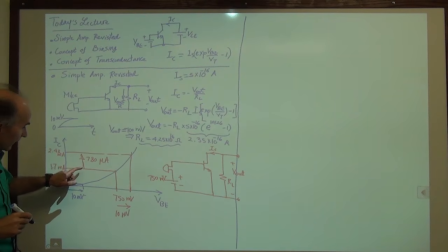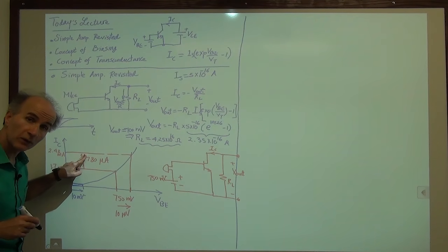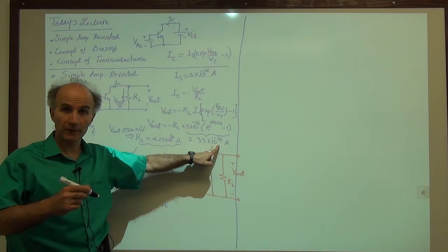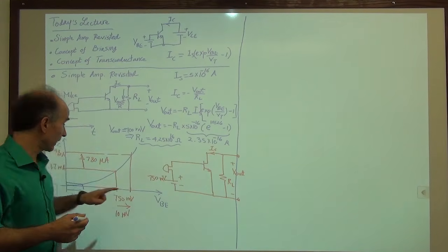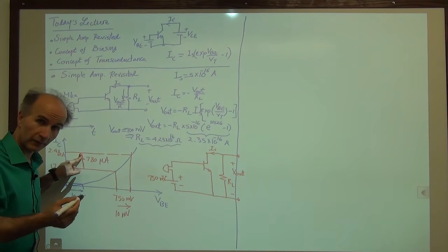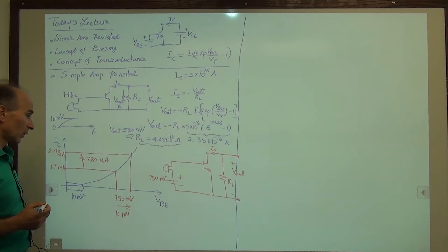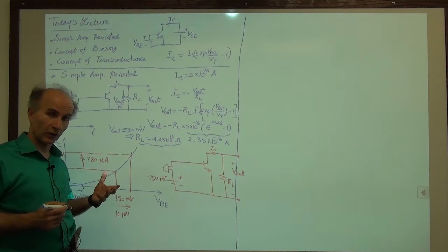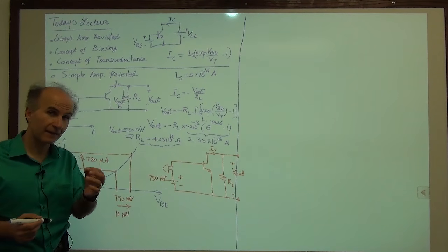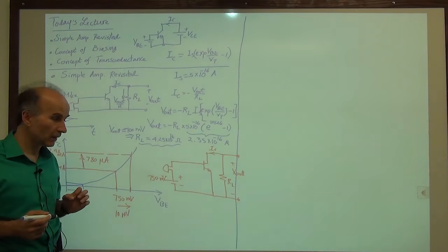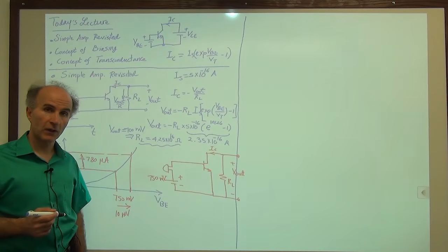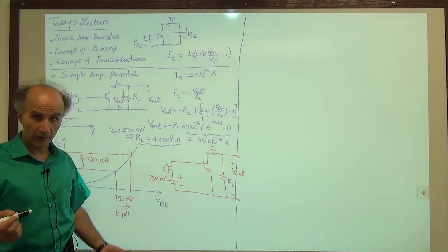Okay, so you see now that the current change in response to the microphone signal is much larger than what we had before. Before, we got only this much current after the microphone signal was applied, but now we have this much current with the signal from the microphone applied. So if I have 780 microamps of increase in the current as a result of the microphone signal, what resistance do I need here to produce 100 millivolts of signal at the output? That's not that hard, right?